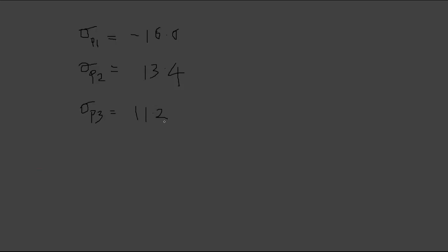Yeah. So you need to draw this in a Mohr circle, right? I'll take this. Sigma 1 is the principal. So I take the tension positive, right? Principal stress. So sigma 1 is this one, right? Sigma 1. It's the largest tensile stress. So this is sigma 2. And this is sigma 3. Compressive stress, right?